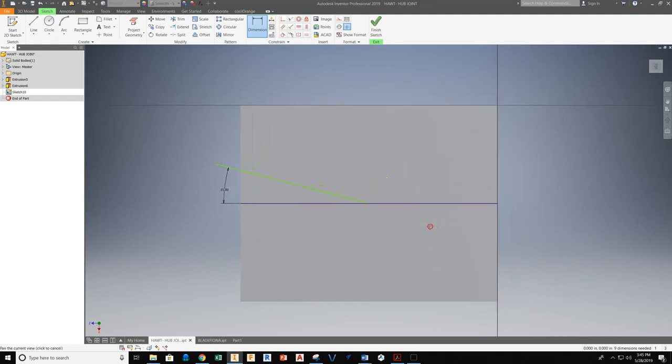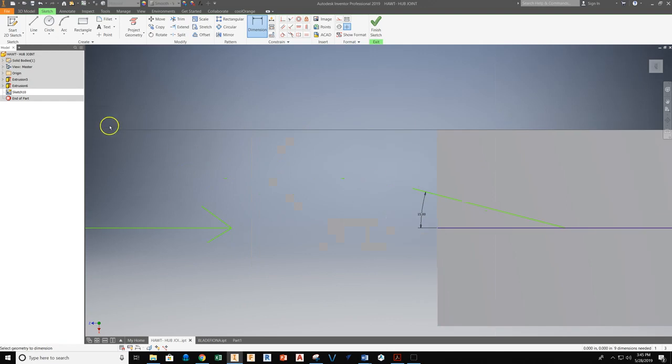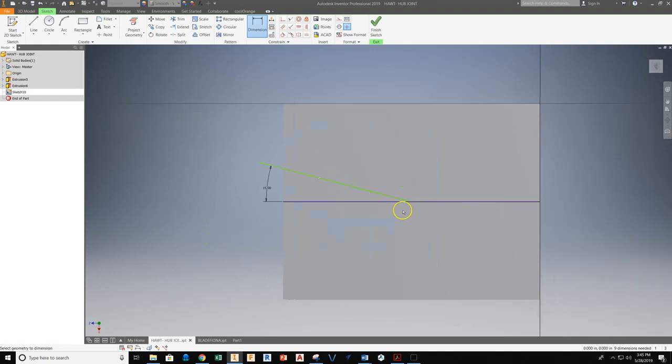So we'll set this up as my angle of attack for my apparent wind, and then I'm going to start working in the airfoil itself. So if my apparent wind is coming at my blade at about 15 degrees, then I really want to set up my angle of attack for my airfoil at a slightly steeper angle, with the idea that an airplane wing, or a wing in general, has a slight elevation to it, so that you have the idea of high pressure and low pressure working around.